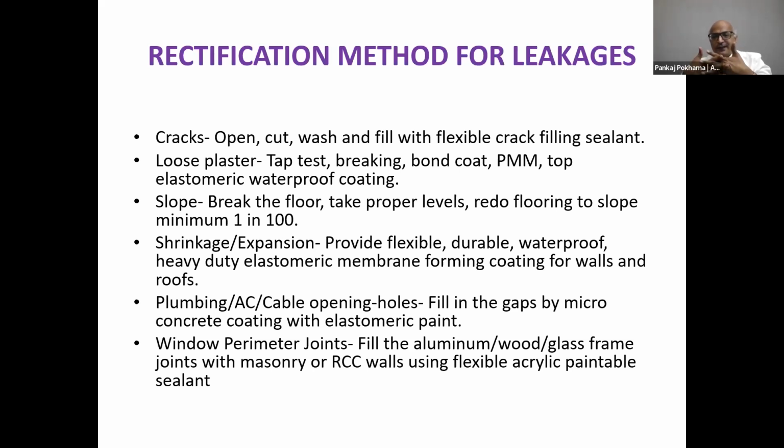So whenever there is expansion or contraction, the wall may expand or contract, but the sealant will not leave the edges of the wall and there will be no crack occurrence. So there will be no leakage through that crack. That's why we say it is a non-shrink acrylic waterproof crack filling compound. Right? So this is the complete description of the product which needs to be treated.